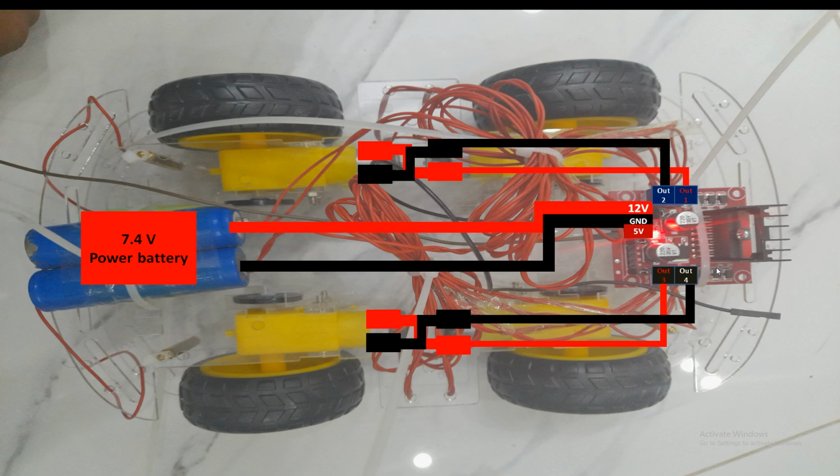Now you have to make sure that whenever you connect this to the 5 volt supply, both of these motors on the top should move in one direction, and at the bottom they should also move in the same direction. So when we do the programming, we will send a pulse. So one pulse will enable this gate. So these motors will move in the same direction. They will act as a single unit. So these two will act as a single unit. You have to maintain their direction.